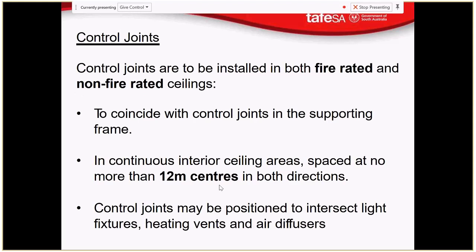But if we do, then we need to provide a control joint in that ceiling somehow. That's to ensure that we don't, well, it doesn't ensure, but it helps to mitigate the risk of having plasterboard cracking in a non-controlled fashion.